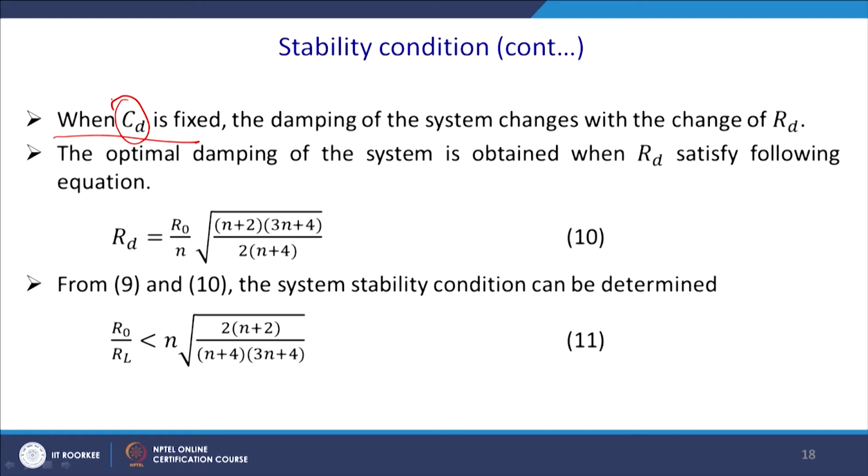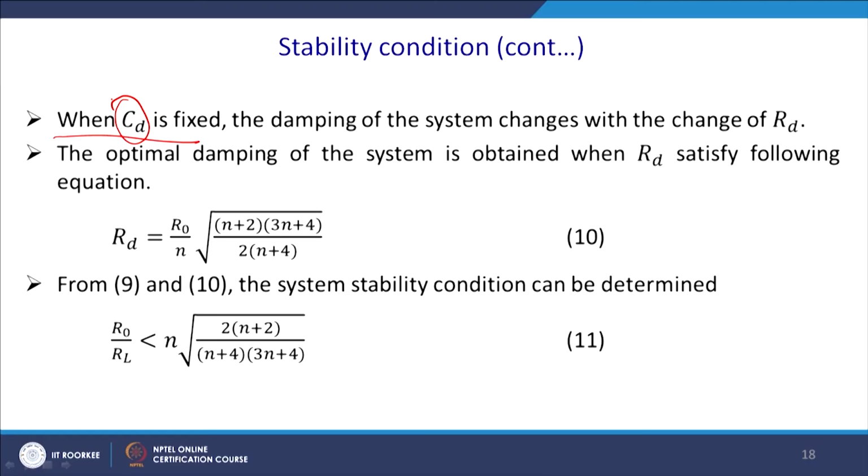It is your task in simulation also, you put those values of R d and check, because in a real hardware setup you may not do that hit and trial. For this reason you take a range of R and you sweep the value of R and see where it gives the best response. But of course, your theoretical results will mismatch, because a lot of parasitic elements come into the picture, and we have to eliminate or account for those parasitics in your hardware.